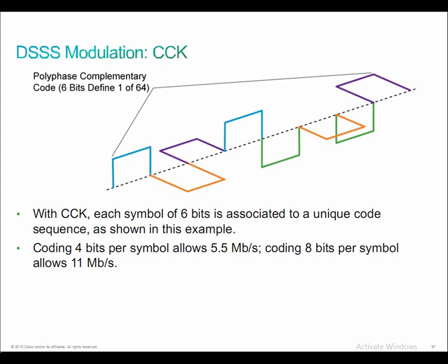We're using the same frequencies, the same wavelengths, and the same bandwidth, the same 22 megahertz wide channel. So we send the wave over that 22 megahertz wide channel. It's a little bit faster than we saw with the previous encoding methods. We send it at a speed of about 1.3 million code symbols per second, each of those representing 4 bits. So if you do the math, you multiply those numbers, 1.3, I forget what the actual full number is.